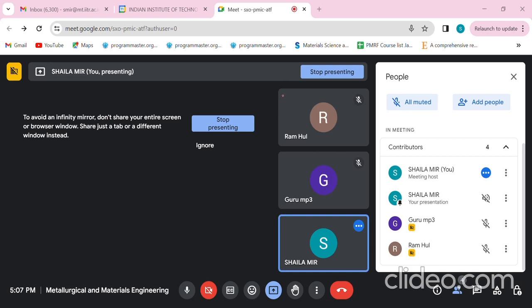While the solidus line is the phase boundary between your liquid and alpha phases, or between your solidifying phase, which is the solid solution alpha plus beta. And your solvus line gives you an indication of the maximum solubility of your component B in component A. So you have to say which of the following is true. Which is the solidus line and which is the solvus line?